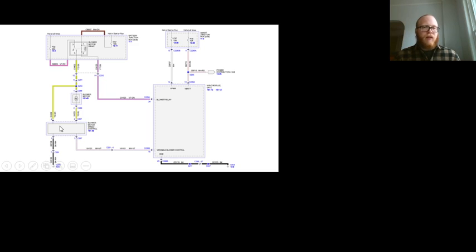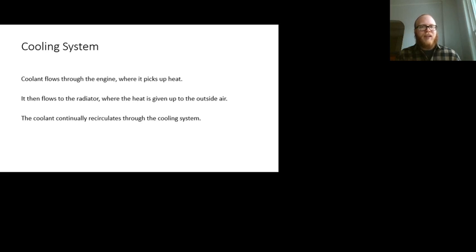100% on time for high speed, 75% on time. So let's say every second, this thing is pulsing 100 times. Out of those 100 pulses, it chose to be on 75 of those 100 pulses, gives us 3/4 speed. And believe me, we'll work on this a little bit in person. It's a little easier that way.